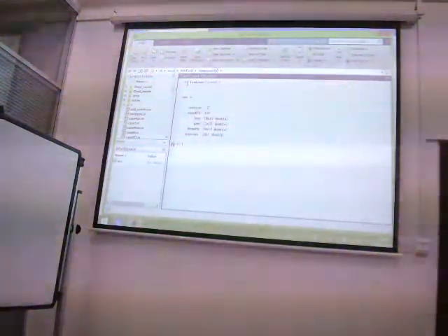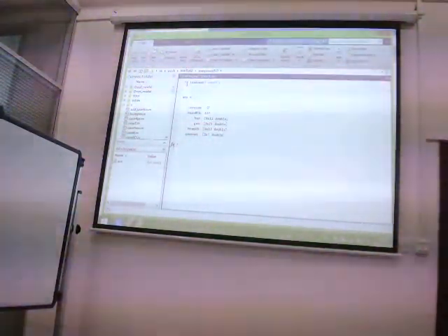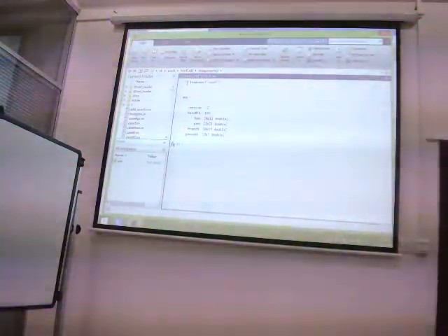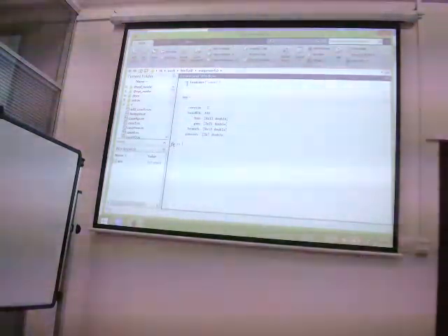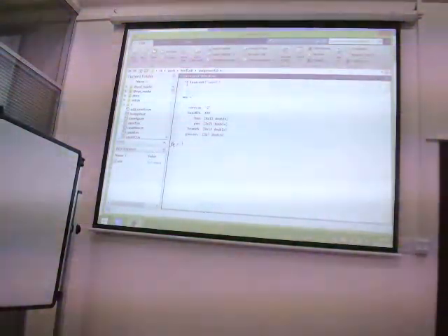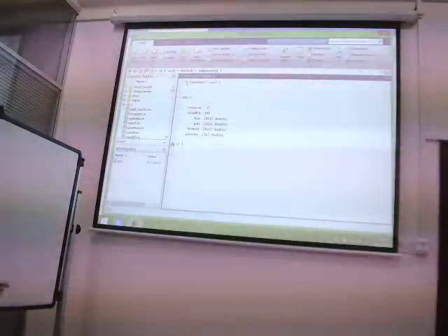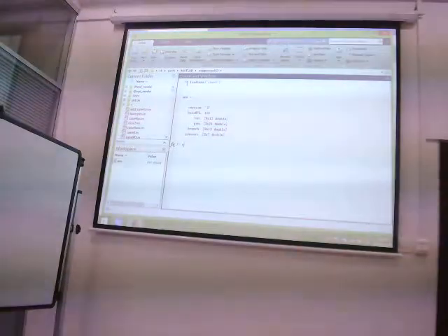Just write this one command, then MATLAB can read the information for the case 9 system. It means the answer gives you the information. We have 9 buses, 3 generators, and 9 branches. It's the brief summary for the 9-bus system. Then just run one command.